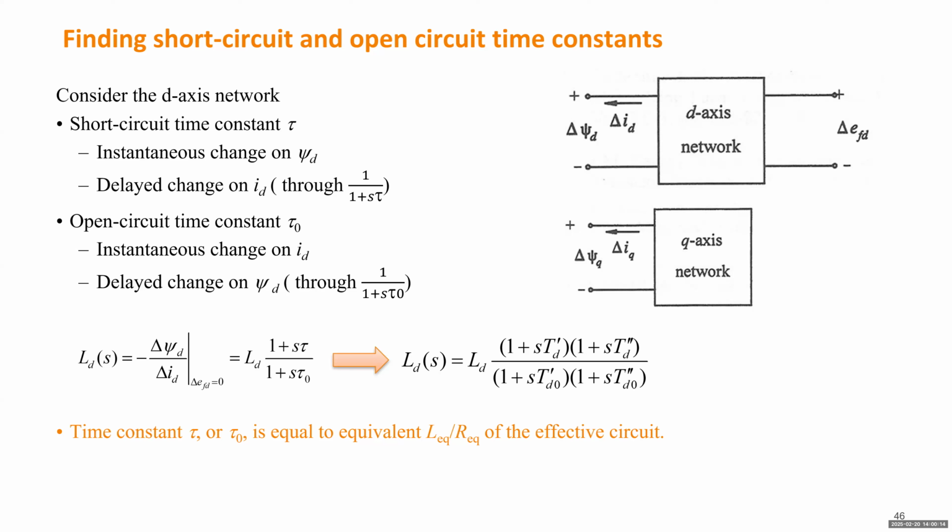Further, if we want to separate the transient dynamic from the subtransient dynamic, you have to add another order. Definitely, if you want to introduce an even faster dynamic than subtransient dynamic, you put a triple prime. If you want to do that, you can. If your generator really presents that complex dynamic, you can keep adding the order forever. But typically, we only consider transient and subtransient dynamics. Just two types of dynamics.